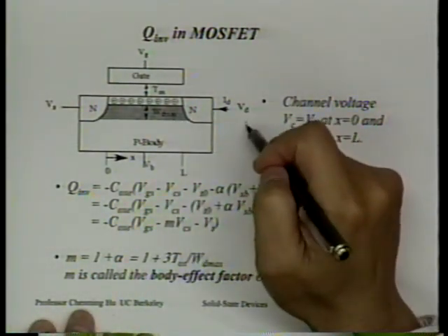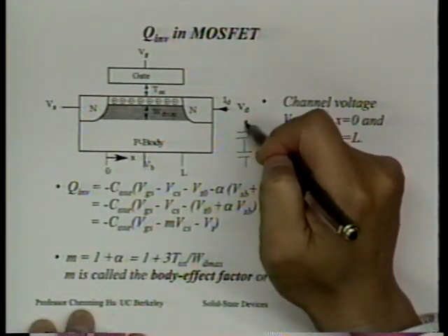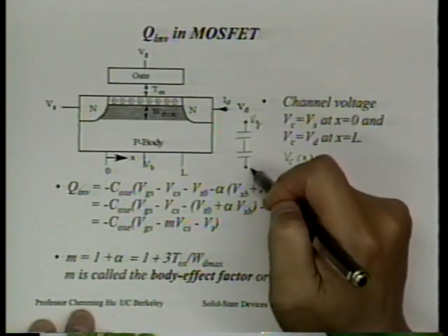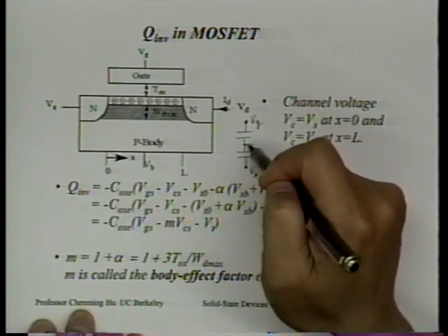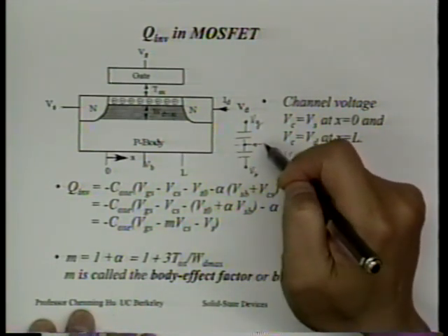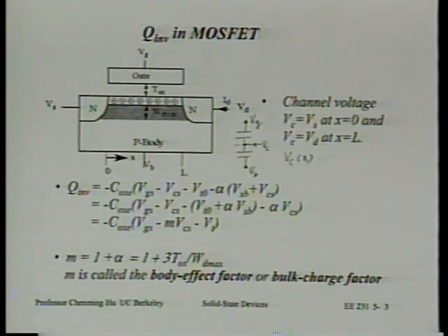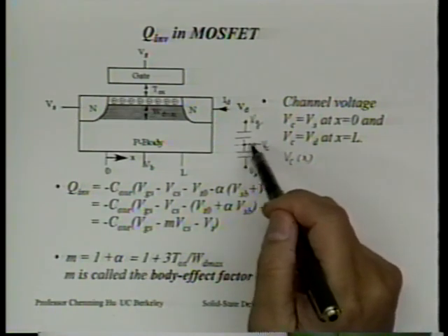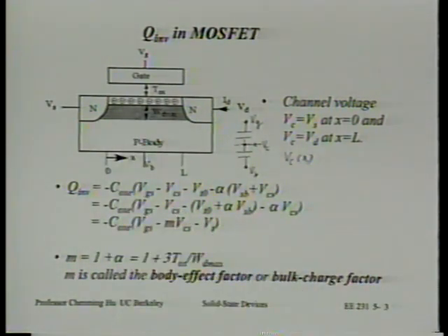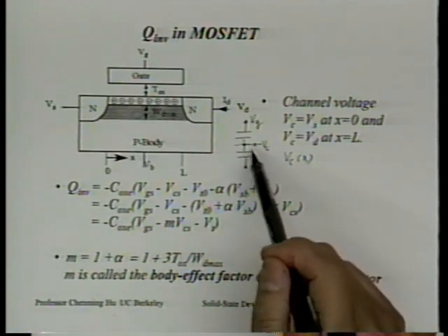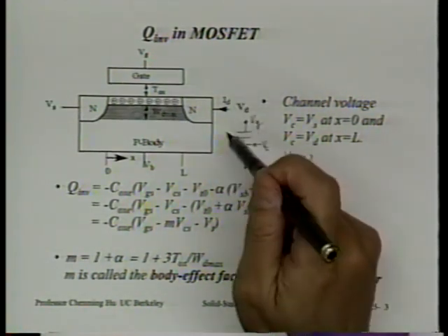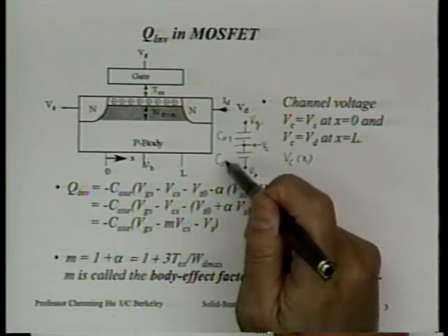So now you have to think, we have a capacitor now. We have a Vg here. We have a Vb here. Now this channel potential, we force this electrode to Vc. Now I want to know what's the charge density at that electrode, that imaginary electrode, which is our inversion layer, which may not be that imaginary when you consider it's a very good conducting layer, so perhaps I should not call it an imaginary electrode, it's a real electrode. So what's the charge density at this electrode that we call the inversion layer, knowing that it's coupled to Vg through Cox and coupled to Vb through C depletion?